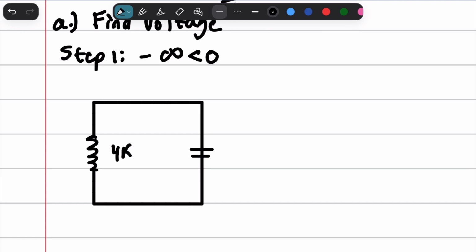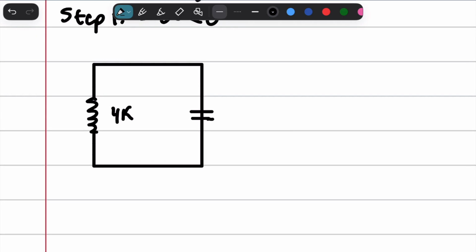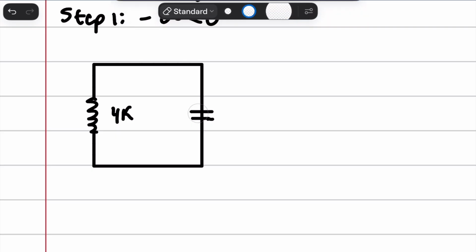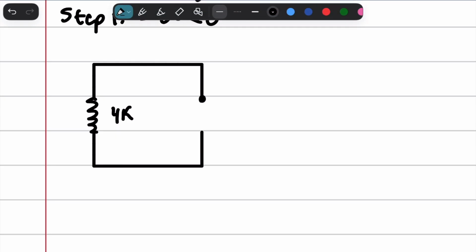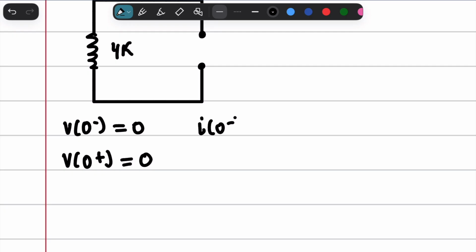And as you can see, nothing is attached to this that could charge anything, just an empty capacitor, right? We're going to expect that this is empty because it's discharged everything to the load during this phase. And we'll just go ahead for formality's sake and call it an open circuit, okay? So we know that the voltage across this is just 0, okay? And likewise, because it's a capacitor, we know that it's also 0.